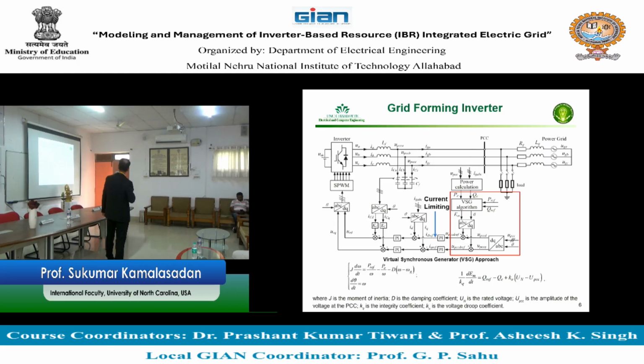So far, another way you can do it, don't worry about the synchronous generator, modeling a virtual synchronous generator. There is a lot of stuff to do for a synchronous generator. Then I look at how the synchronous generator can be modeled very easily. You model the synchronous generator performance very easily on what we call a droop behavior. Droop means when the frequency changes, what I need to do is push the active power. I don't care about angle and other things. I change the frequency, push some power, and maintain the frequency. Voltage changes, I push some reactive power, and maintain the voltage.